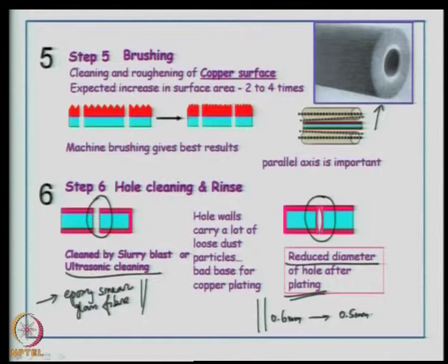And when you insert a component here later, you will see that the component is not fitting into the through hole wall. So, what you will try to do is force its entry into the through wall, and as a result you will break the plated copper, which will result in an open.